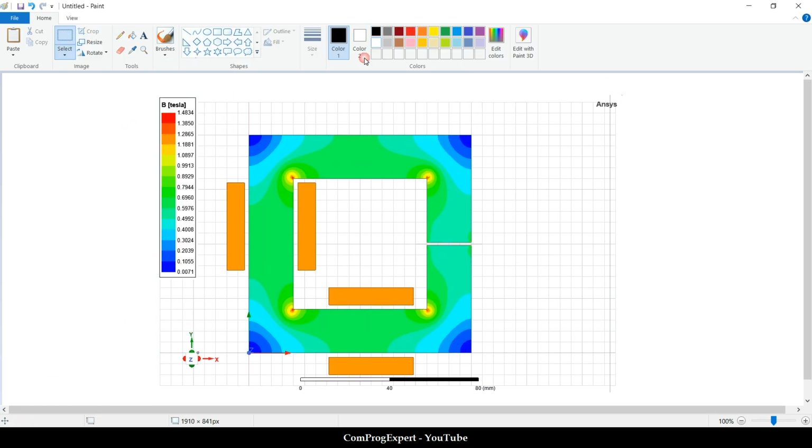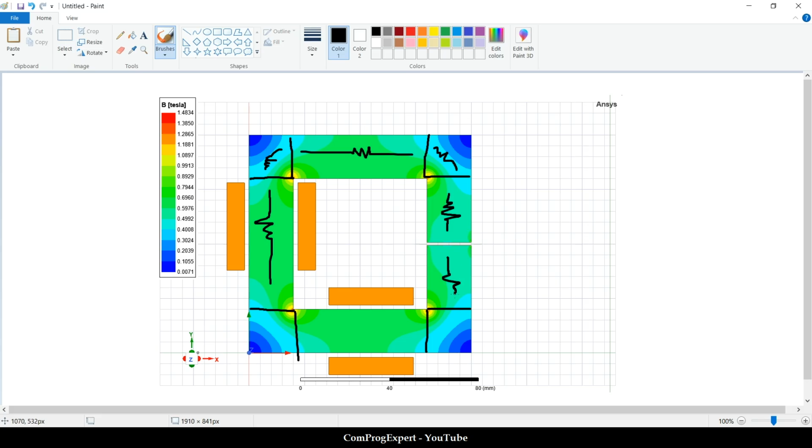So if we consider, for example, one reluctance here, one reluctance here, one core reluctance here, one core reluctance here, another one here, here, here, okay? And we divide the iron core into different parts. For each reluctance, we can calculate the permeability depending on the level of the excitation and solve the circuit.